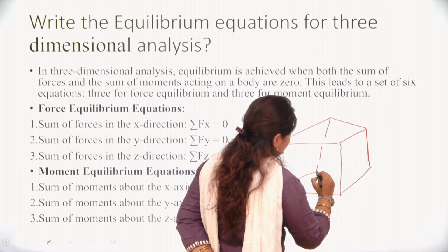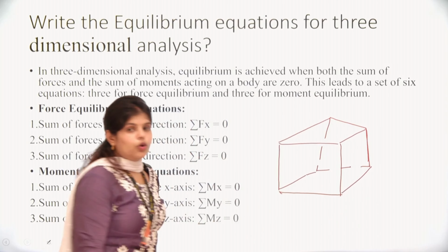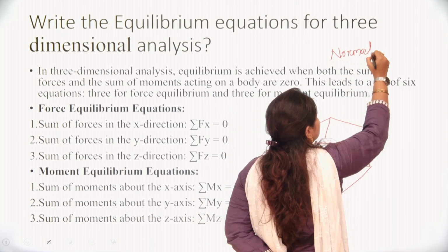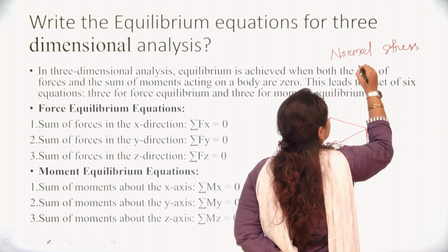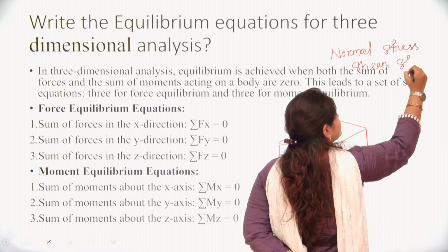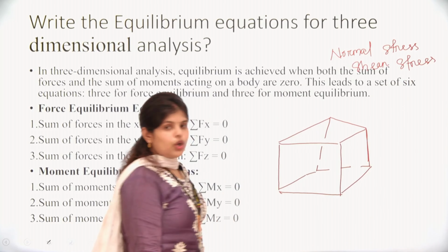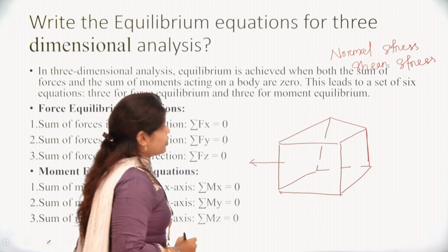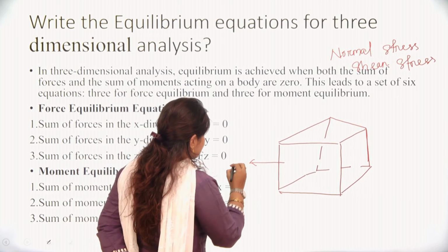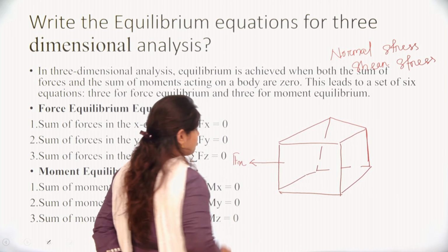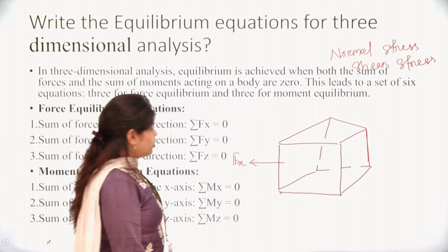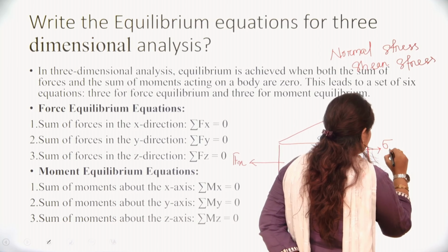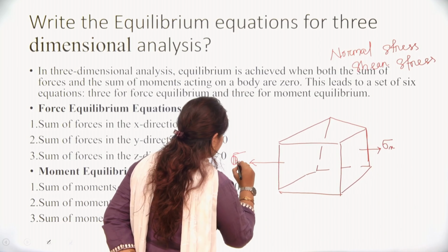When we take the stresses, we need to have the types of stresses in mind: we have normal stress and what? Shear stress. So in the x direction, here we will have the normal stress, let it be sigma x.